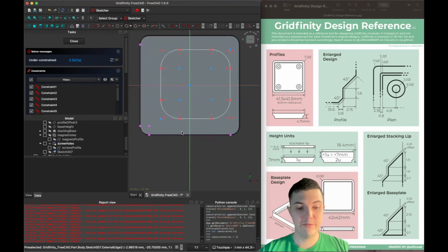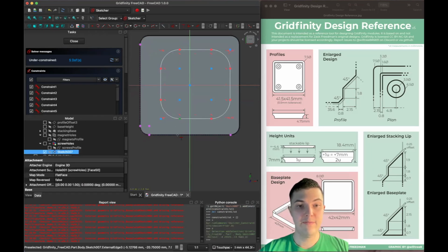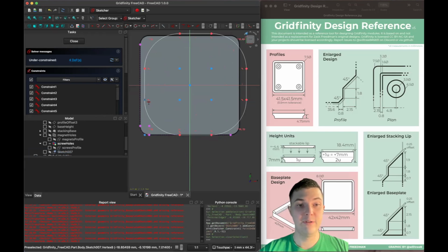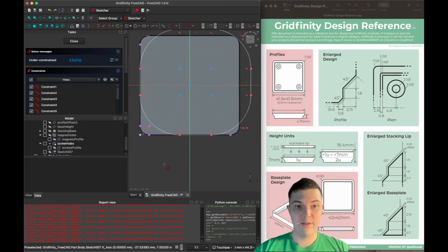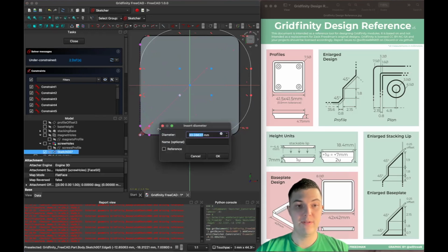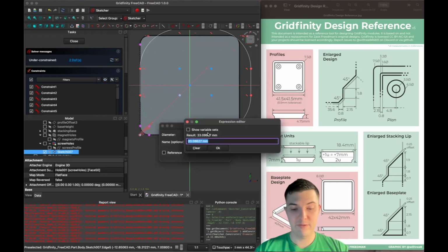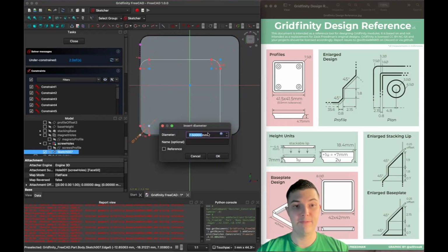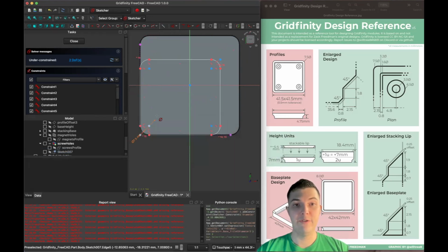And what I'm going to do is I'm going to create a coincident constraint for this point on that edge and this point on the left edge. Now I need to constrain this diameter to be global variables and fillet diameter 3. And now, as you can see, every fillet was updated.